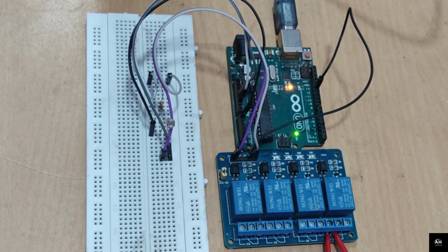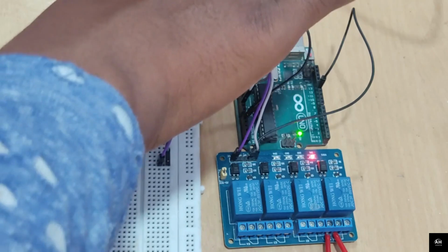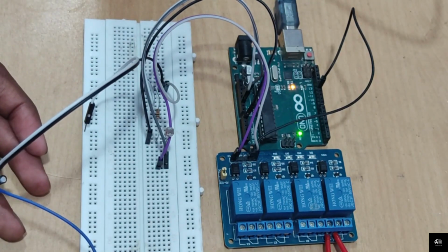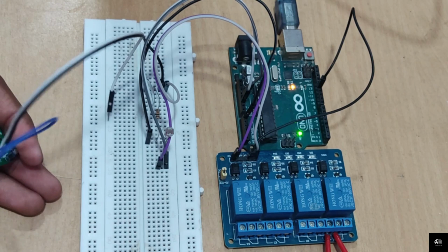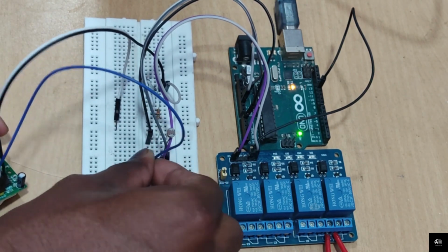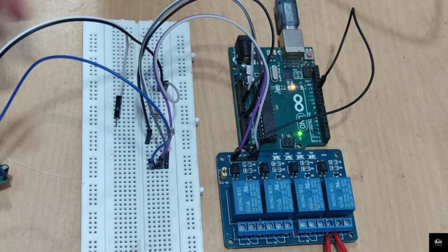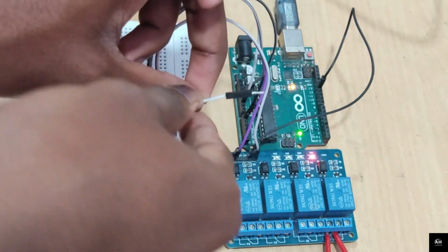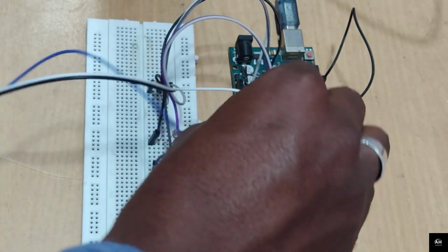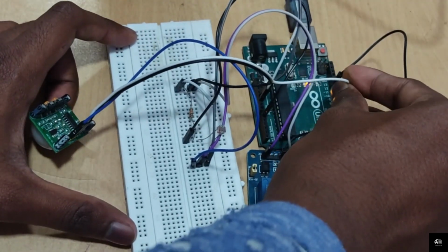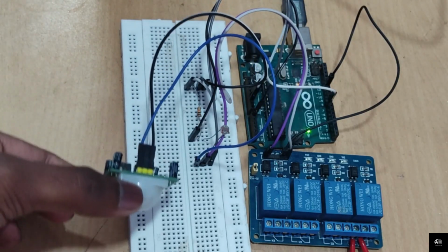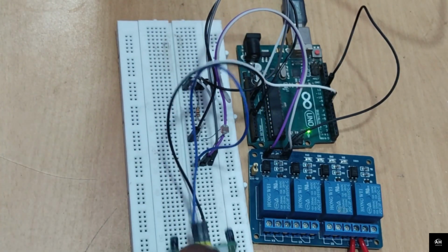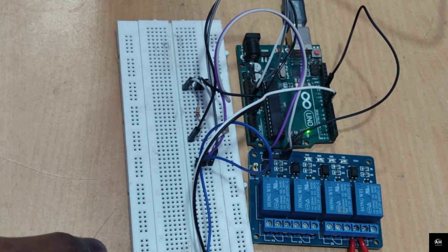So I will just connect the ground pin with the ground that we have extended onto our breadboard. I have connected that, and now we will connect the 5 volt with the 5 volt on the Arduino board through the extension, and we will be connecting the digital in onto pin 8 of the Arduino board. I will just connect it over there, and once we are done with it, we will just put our motion sensor towards the opposite side like this.